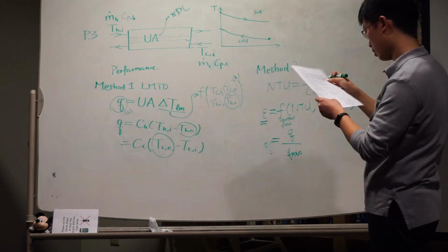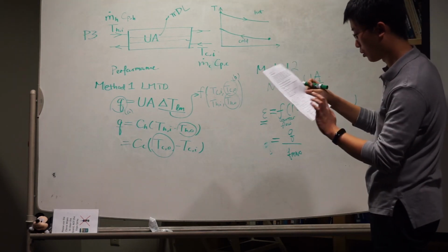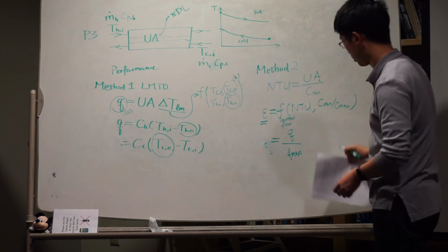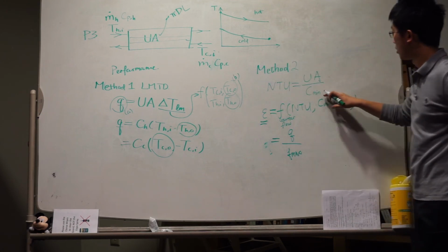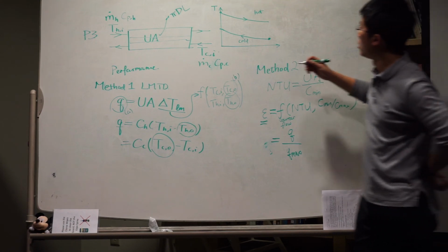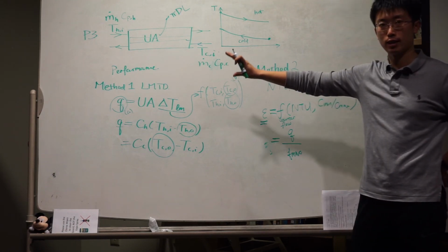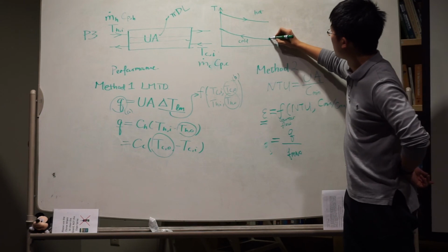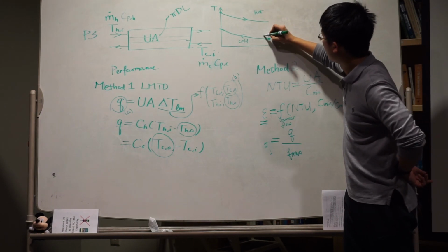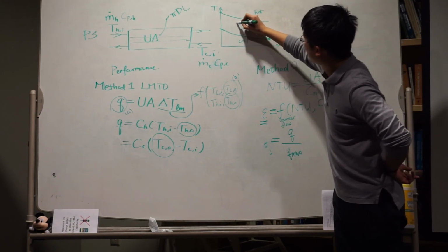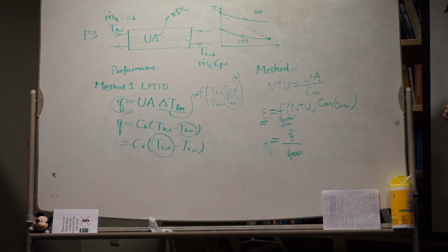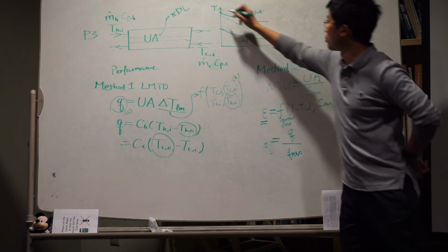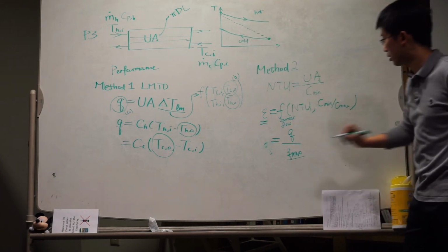In this case, after a simple calculation, we know that the cold fluid, which is the blood, has a smaller heat capacity rate. If you have a perfect heat exchanger, the temperature on the cold side will exit at the hot side entrance temperature. And this much heat is what this Qmax is.